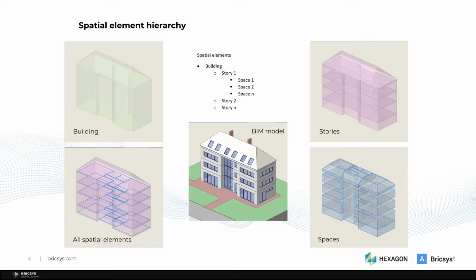So this geometry already contains a lot of information that we can harvest from it, such as total floor area, building footprint, and we can relate this data with other model element data to derive further information, for example, lot coverage, and lot to building ratios such as floor area ratio, floor space index, or building coverage ratio.